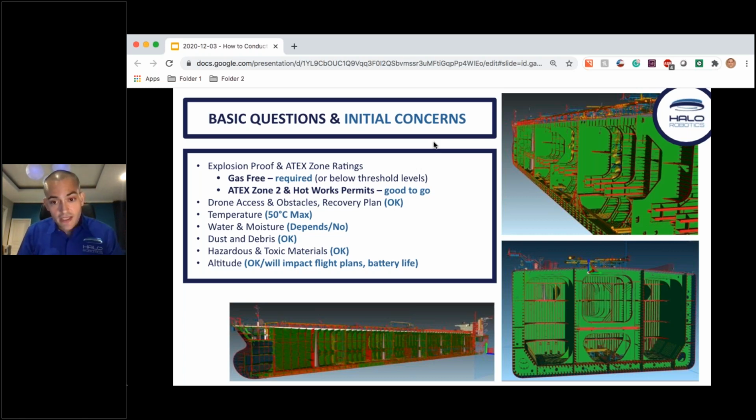The traditional method would be that you'd also have to clean it out so that people can go in safely, because there are corrosive materials, etc. That is where the Helios 2 is meant for those types of environments. So yes, the moment that it is gas-free is the moment that you can start to do drone inspections on those assets, as long as the hazardous toxic materials aren't obstructing the actual inspection that you're trying to conduct.